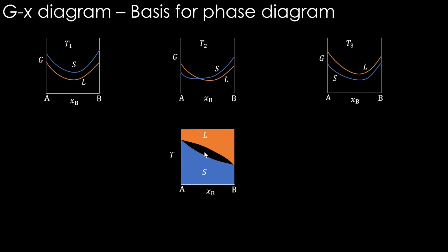Take multiple compositions from left to right, take them to very high temperature, cool them, track where the liquid to solid transformations happen, and then take those points from the cooling curve, the temperature versus time curve, to the phase diagram. That's how we constructed it experimentally, right? So in this case, you see the same isomorphous diagram has come, but completely through thermodynamics. Okay, this idea is what the CALPHAD tools, or the computational thermodynamics tools, are going to do.